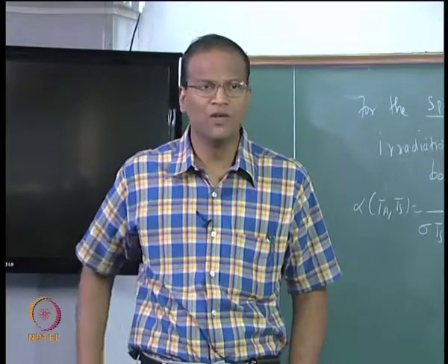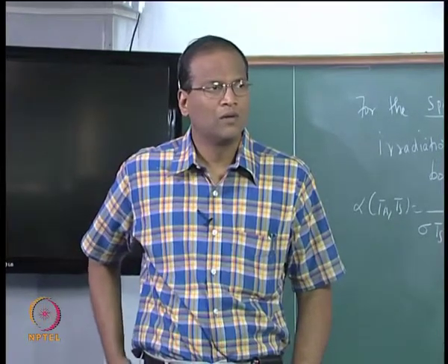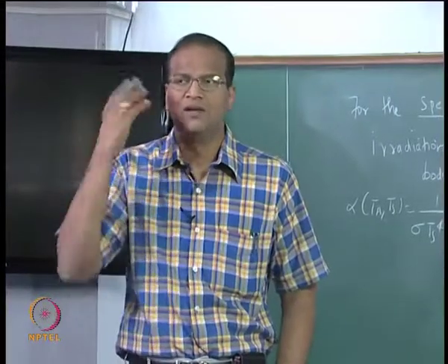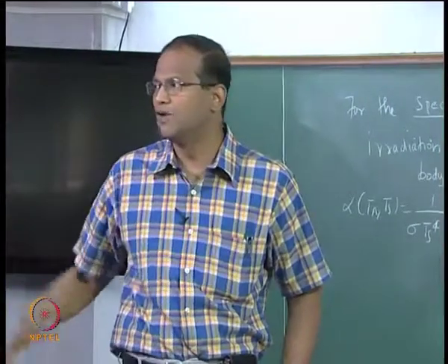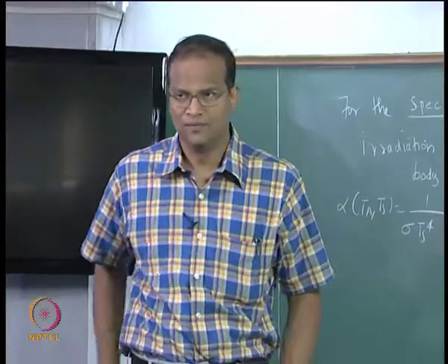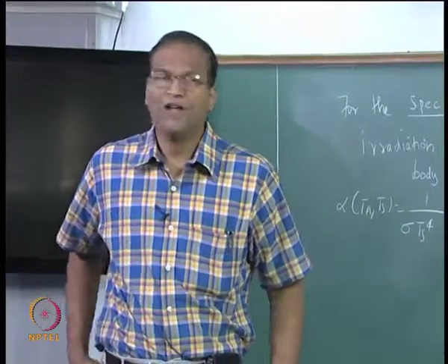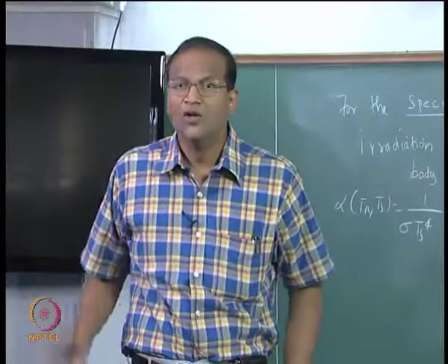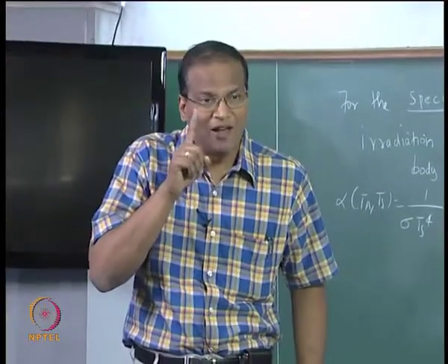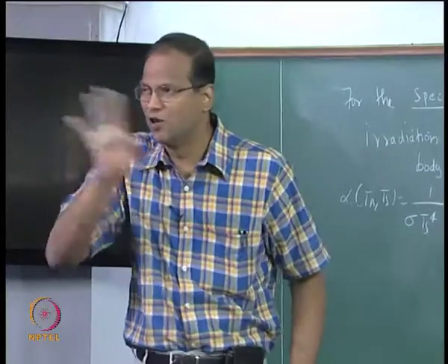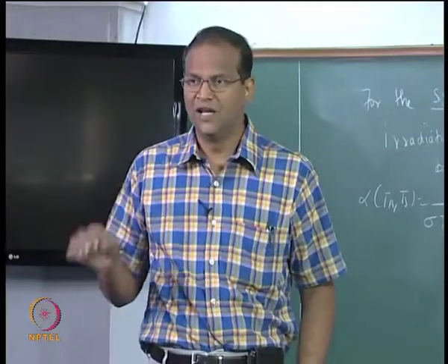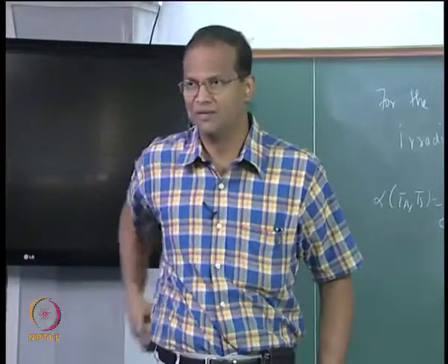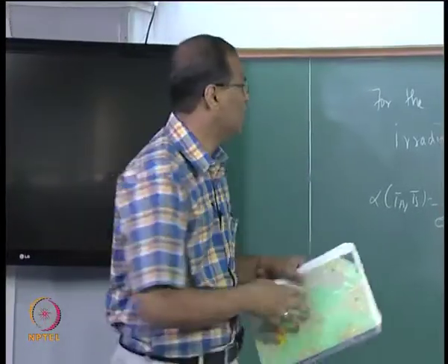What is the information you need? Right, without irradiation, or I should tell you at least this is from a black body, or I should give you I lambda I, otherwise you cannot do anything. If I give you emissivity, if I tell you the temperature, you can use the F function chart and calculate. Therefore, if alpha lambda versus lambda is given, that is not enough. I should give you the nature of the incident radiation, or I should tell you from where it is coming, correct. So, I will give you the distribution.